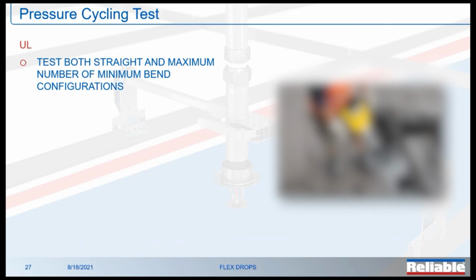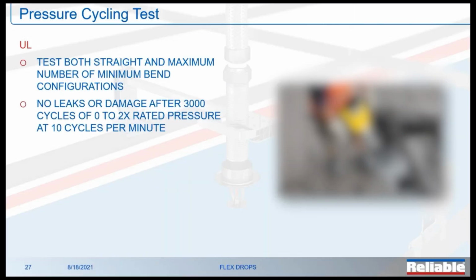We're going to pressurize these things. We're going to cycle 3,000 cycles between 0 and 350 psi. If it's a 175, we're going to do that at 10 cycles per minute. And we're going to make sure that afterward we do not have any leaks.